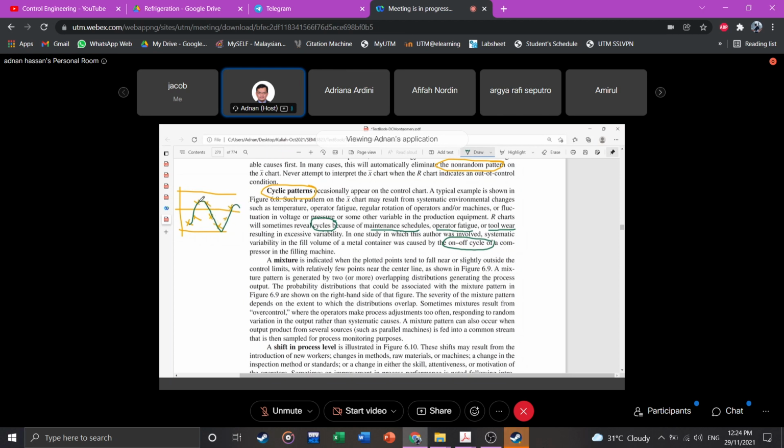In the morning, maybe okay, in the afternoon it's going to be hot, toward the end of the day it's going to cool down again. Or maybe something is loose, in terms of a component which is joined, for example using a screw or anything that can join two parts. The cyclic pattern shows that the mating part is wobbling, for example.